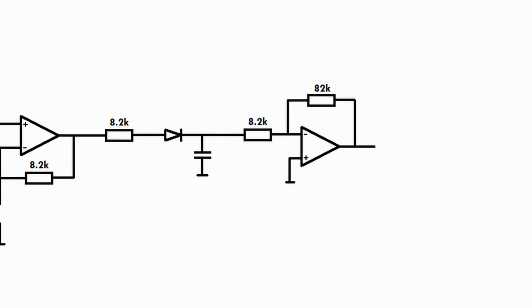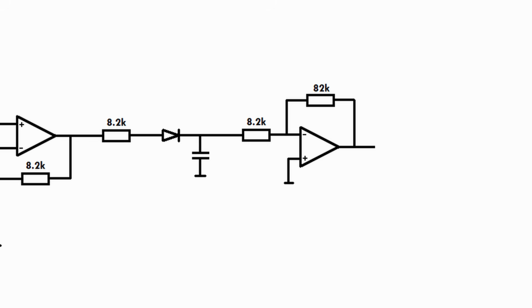An inverting amplifier, again, amplifies the signal, but it also inverts it. So if you put a positive voltage into it, you'll get a negative voltage out of it. Which is useful because it means that it converts our positive voltage on the capacitor into a negative voltage, which of course we need to power the gate of our JFET with.